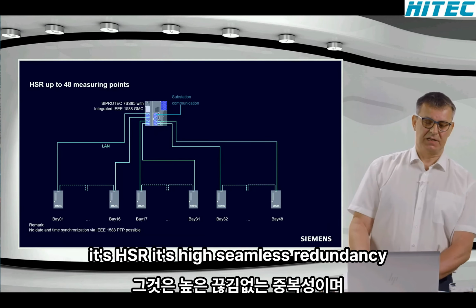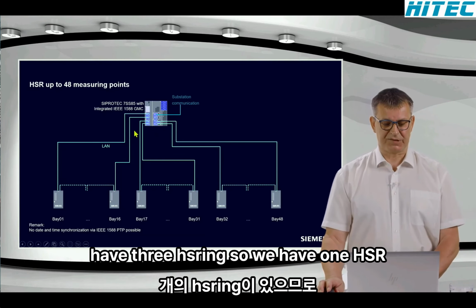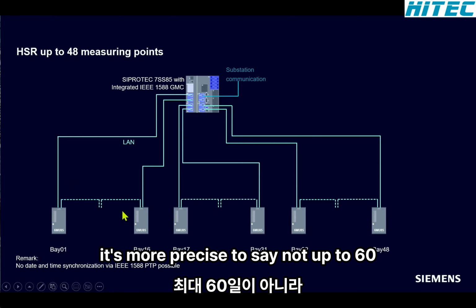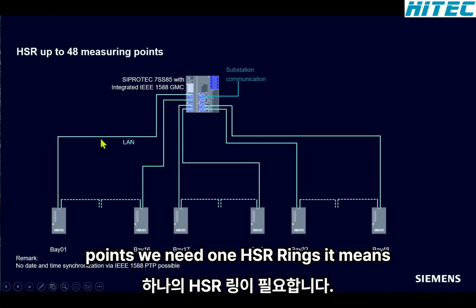It's HSR, High-availability Seamless Redundancy, and here in the maximum configuration we have 3 HSR rings. So 1 HSR ring will be sufficient for a configuration with up to 16 bays. It's more precise to say not up to 16 bays, it's up to 16 current measuring points. So for up to 16 current measuring points, we need 1 HSR ring.